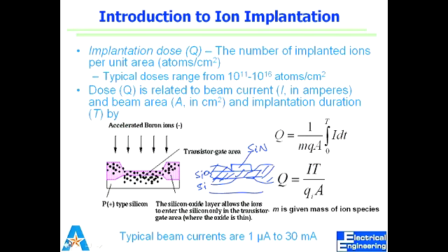Why is the implantation dose measured with atoms per unit area instead of atoms per unit volume? Yeah, that's a very interesting question. Before the dopants get incorporated into the substrate, all we can control is the area where we impinge them. Once they get inside, yes, now their profile is what we will see many models. So then it is a three-dimensional problem. So the doping concentration will be measured with atoms per unit volume. It's not doping, it's the dose of the beam